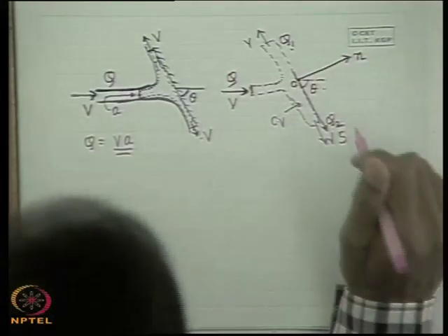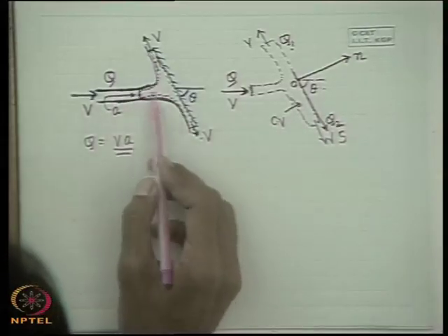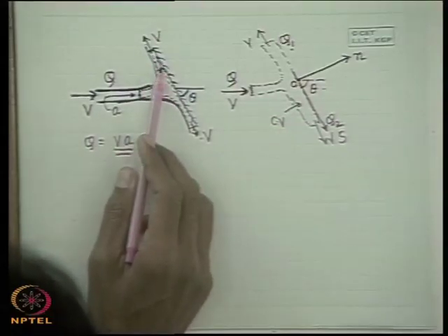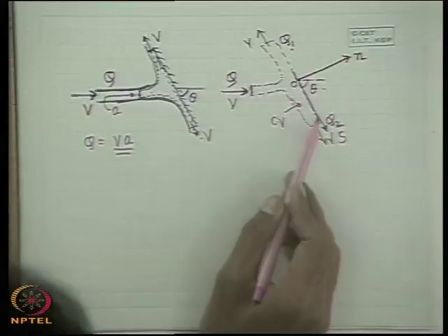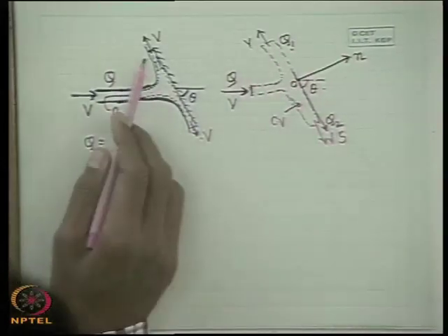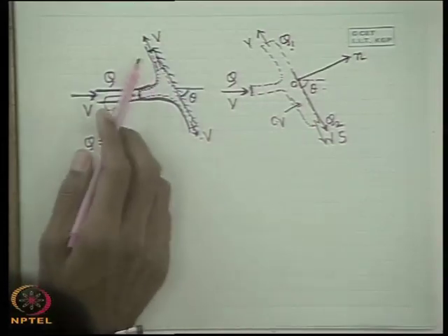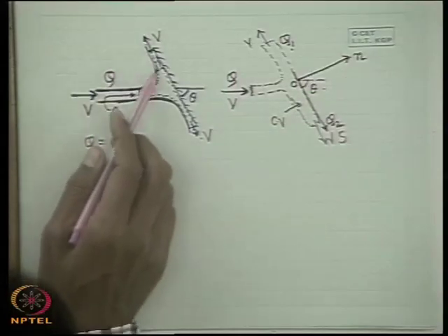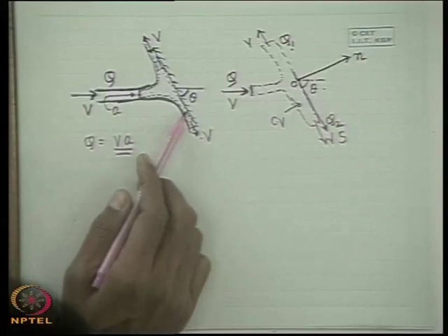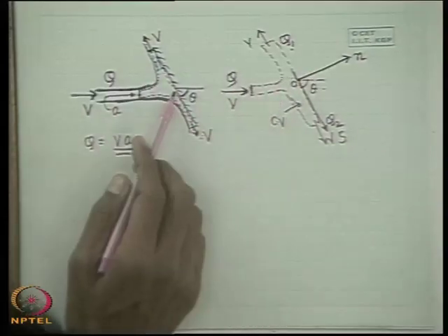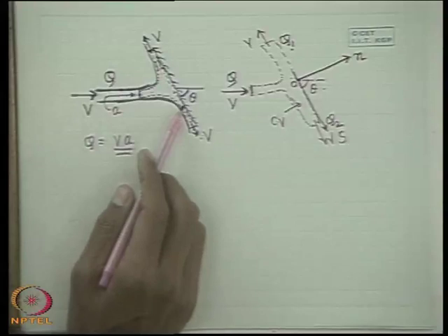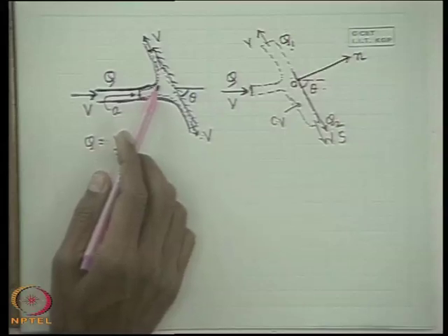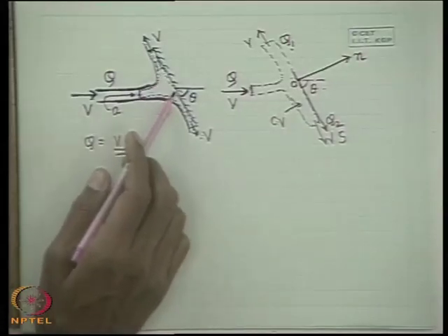This trick is because, with the assumption of inviscid flow, there is no frictional interaction between the plate and the liquid. So, the net force acting along the direction of this plate on the fluid element will be 0, because the outlet fluid stream will be flowing along the plate. Therefore, any force along the plate acting on this control volume at this surface would only indicate the frictional effect, because the normal force between two contact surfaces always acts perpendicular to the surface. So, any force acting parallel to the contact surface means the frictional effect.